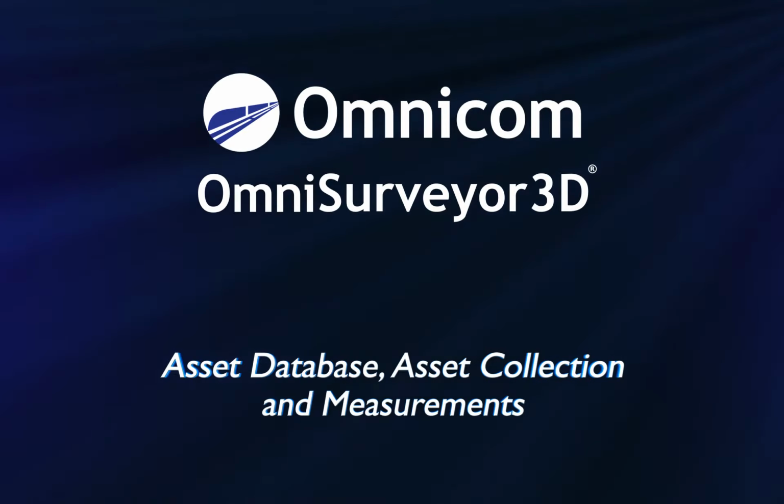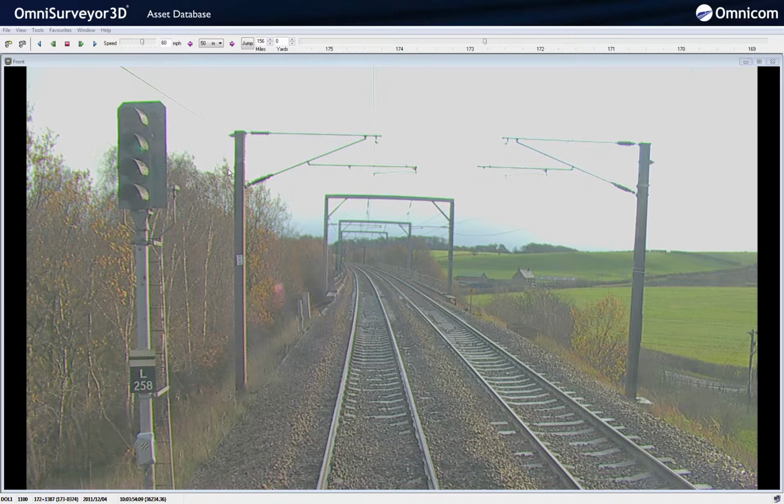Welcome to the OmniSurveyor3D video tutorial for the asset database, asset collection and measurements. In order to view asset details, collect assets or save measurements, you must be connected to the database. To connect to the database, click on the Open Database icon.